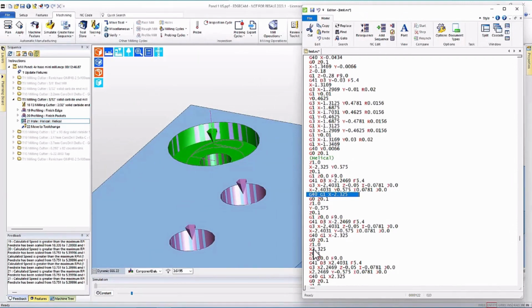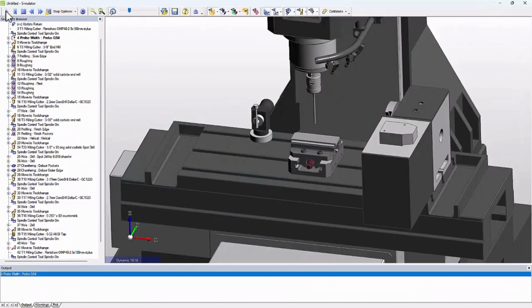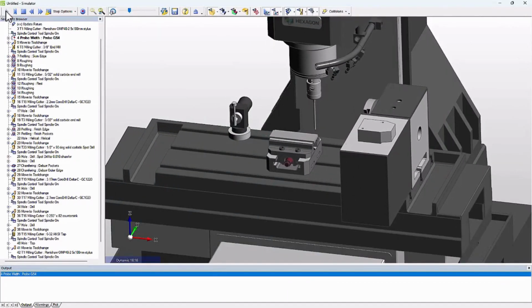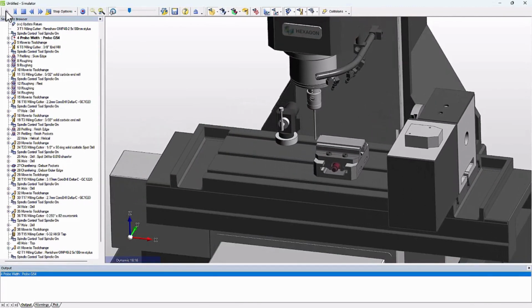So in summary, when we're in an EDGECAM milling cycle and we wish to use cutter compensation, we can do that without worrying about whether we'll have errors in the NC code because of cutter compensation rules. If we want lead-in moves, we can also request them. Taking a look at the machining process, we see the probe coming in to set up the work coordinate system.